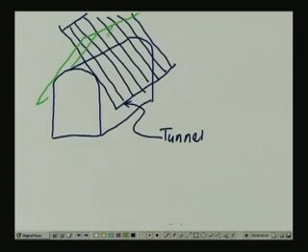So, here you have got this type of joint. Now, you can see that this particular joint configuration is going to be bad for this tunnel construction, because this much of wedge of rock just above the ceiling of the tunnel will always be prone to failure or collapse within the tunnel volume.